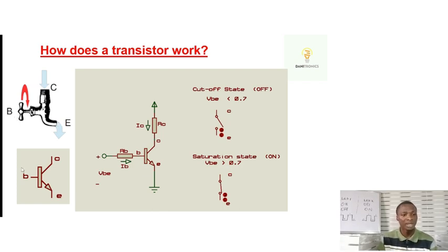So bring it out to a transistor. Based on the control you give to the base, it will determine if current will flow from the collector to the emitter. And this is the easiest way to bias a transistor, to connect an NPN transistor. We have a resistor connected to the base. We have another resistor called RC connected to the collector. They are just doing the function of current limiting, opposing the flow of current so as not to damage this